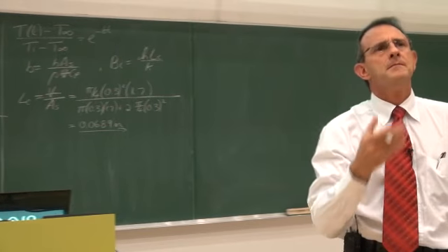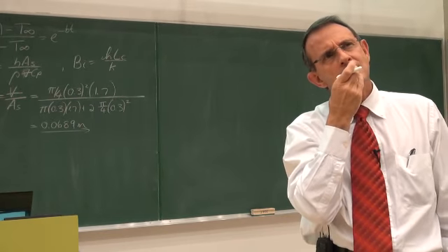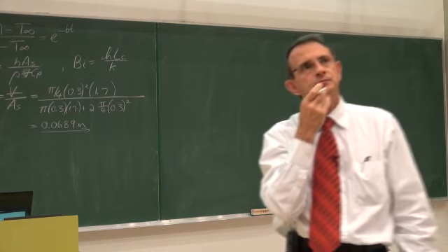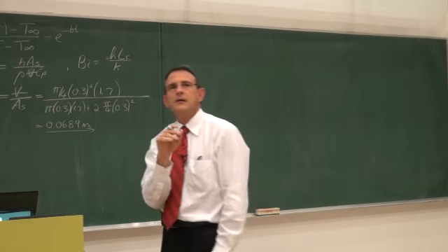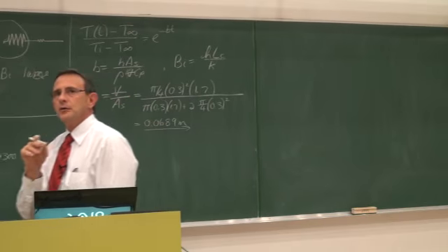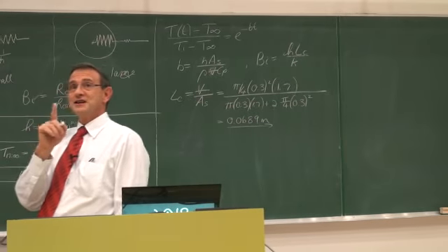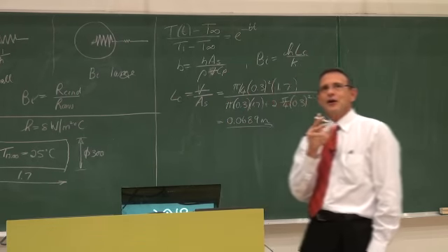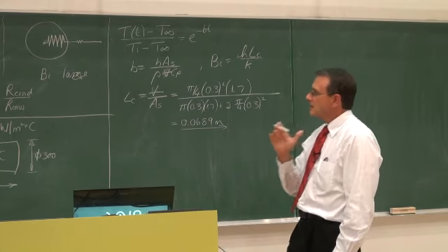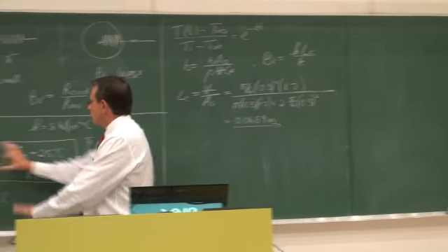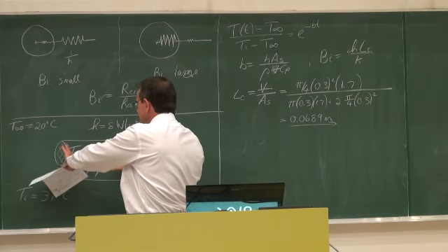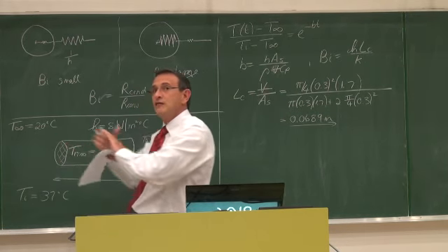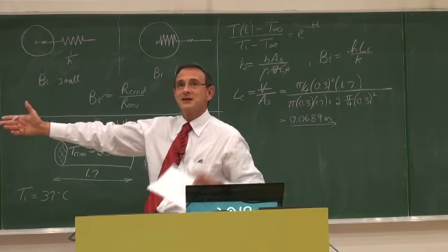So, Prof, just one thing. Because it falls under the long cylinder category, you do not then have to apply what you gave us under the criteria for the characteristic length. It is not a long cylinder. Okay. A long cylinder would be a cylinder where usually we do not look at the end effects. So it would be a very, very long cylinder, and the longer the better.